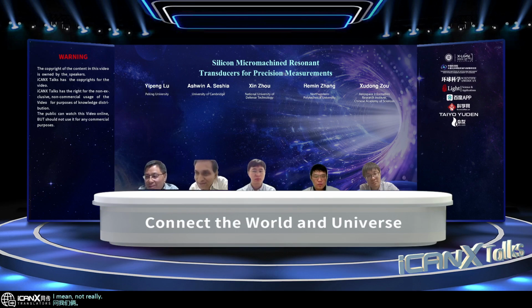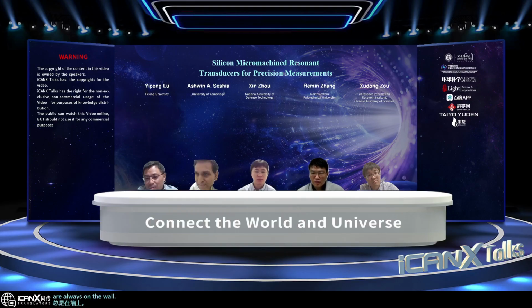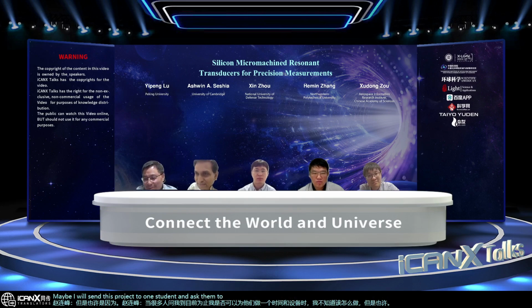I mean, not really a question for me, I think, but he does. You don't imagine that I'm doing the piezoelectric material and MEMS, yeah. Mostly I'm doing the transducers. What I do is low Q devices actually. We want the bandwidth higher. So the first thing I'm thinking about for the timing resonator is, as you mentioned, Ashwin, the material probably has some limitation for the Q, the material loss, not as good as single crystal silicon. Also maybe there is always some contact loss. But quite many people ask me if I can do a piezoelectric timing device for them. So far I don't know how to do it, but maybe I will assign this project to one student, and ask them to look into that.